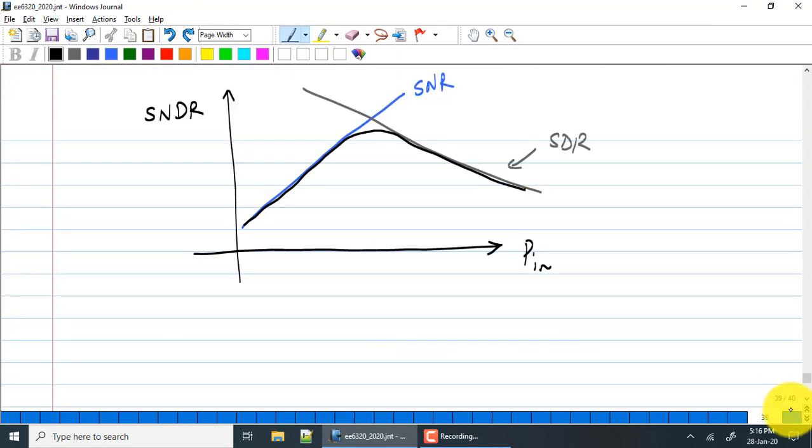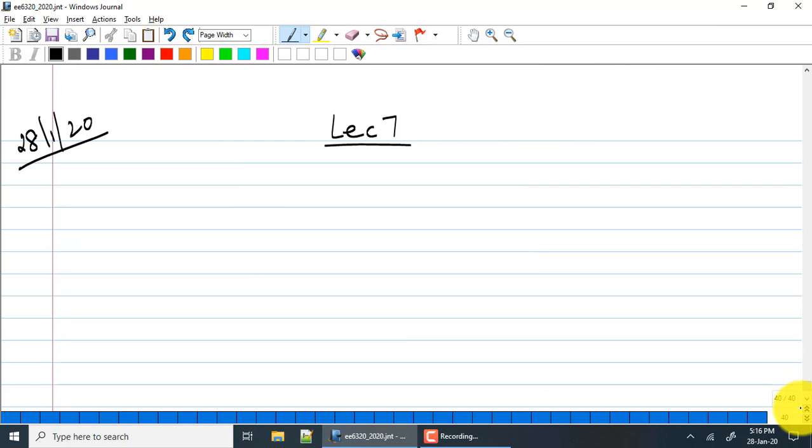Unfortunately, this is still not good enough for a receiver, because for a receiver, very often you will not be having such a high input power so as to saturate the receiver. At least not saturate the front end. By the time you hit the end of the receiver, you will indeed be saturating. You should be, so that you get enough gain through the receiver chain, so that at the end you have a sufficient signal going into the data converter.